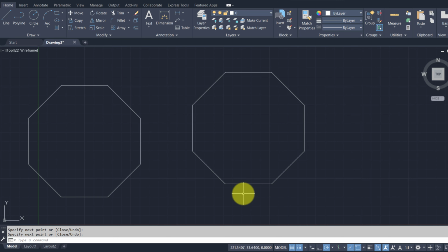What I'm trying to say is, this polygon I constructed using the increment of 45 degrees. Earlier I calculated 0 plus 45, 45, 45 plus 45, 90, 90 plus 45, 135. Like this I added. I don't want to calculate in such a way. Why? Because if I make any mistakes while calculating the angles, then the polygon will not come properly. Each side adding 45 degrees is not an issue. We can draw any number of sides, 10 sides, 20 sides, 25 sides. During that time, if you go for adding the angles, you may miss any one angle. To avoid such confusions, we know the increment, right?